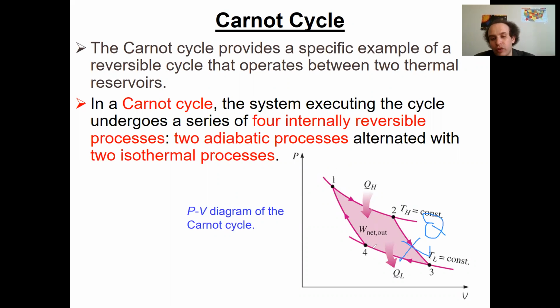You go from 3 to 4, and you cool it, right? And it's isothermal cooling. This heat will go out. And you may also realize that here work will be done on the system. And eventually at state 4, you take out your cooling, and again it will intrinsically shrink until you go to point 5. And here it will be adiabatic compression. No heat transfer here again. So adiabatic, let's see.